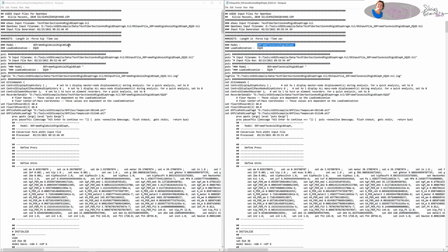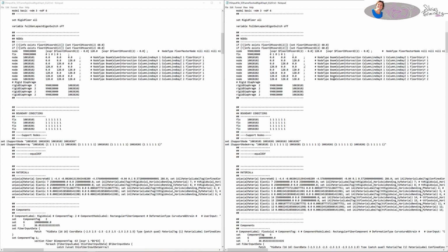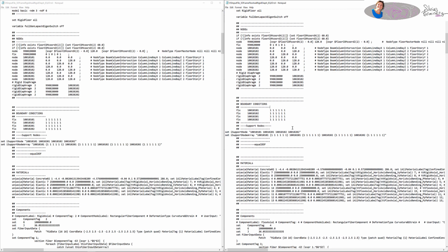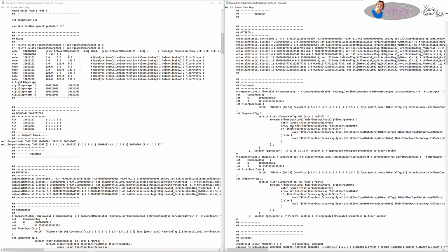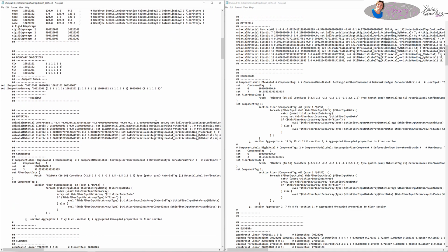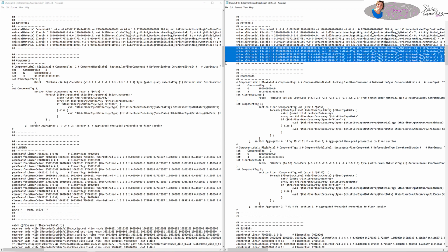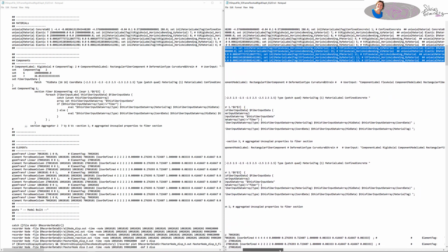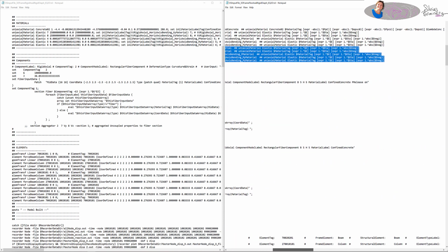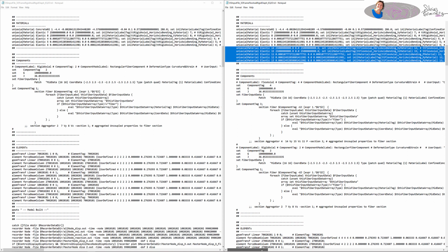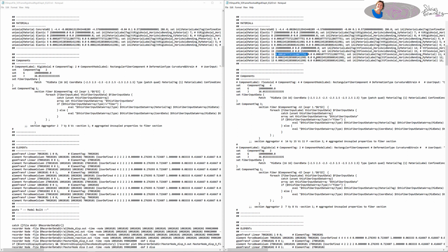Now look at the actual OpenSees input files. On the left, I have the one with the beam with a PM interaction, and on the right, I have the one with the released axial, so no PM interaction. You can see that the initial input is pretty much the same. They both have rigid diaphragm input, but for the second one, I need to define 2 different sections for the columns and the beams, but also you have an additional component to your fiber section, which is the P release, the additional infinitely flexible section in your section aggregator. And I'm going to get to it right there.